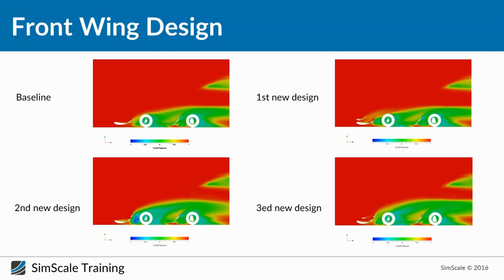So that's why the front wing needs to remain to a certain size, but not too big. Otherwise you spoil overall energy, and what is created in the diffuser is going to be less downforce, less efficiency. If you think of the front wing as well, it's a less efficient component compared to the diffuser. That's right. The downforce to drag ratio it generates is less efficient than the diffuser.